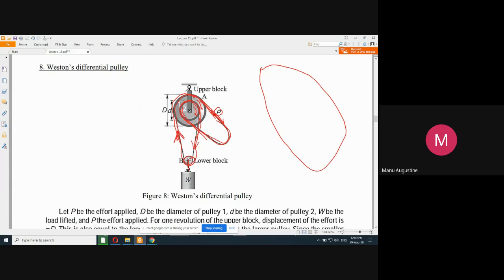So basically, if you have understood the mechanism of how one single rope wound around two step pulleys can simultaneously pull out the rope and provide the rope at the same time. So here what is happening, just look at this junction. Rope is being pulled upward from this arm and rope is being supplied back from this arm. But the rate at which the rope is being pulled and the rope is being supplied, they are different.